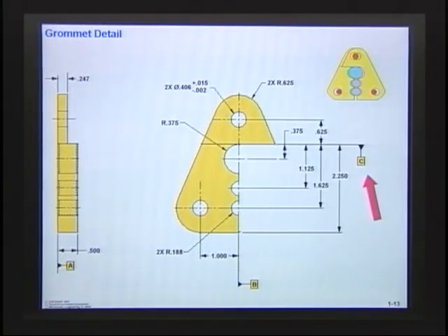All right, the next step that I had to do was qualify the datum features. Remember, that was the second part. Qualifying the datum features, this back face, that's where it mounted up to the bulkhead. I put a flatness on this face within 5. Now, why a flatness within 5? If you remember, the requirement on the bulkhead is we couldn't have a gap any more than 10 thousandths. Remember, on the bulkhead I had a flatness within 5, and this one I had a flatness within 5. At worst case, that could give me a gap within 10. That's where that flatness came from.